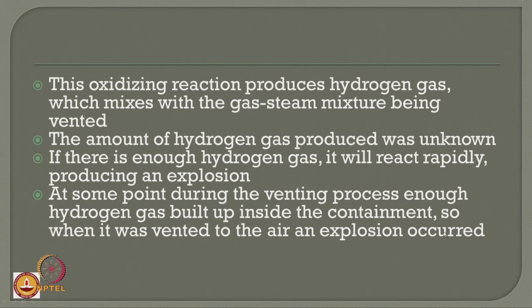So, you can see the series of faults that occurred. Earthquake started, earthquake damaged the reactor, it resulted in power shutdown, reactor was stopped, moderator rods introduced, there is no coolant supply available, external power was brought in, tsunami came, external power was damaged, there is no power backup available. After a few hours, people brought up battery supply, even the battery supply drained out, but they could stop the reactor, but they cannot stop the heat. They pump in water, they want to disable or relieve the cooling system. This water produced hydrogen gas, released pressure, resulted in explosion. You see, these are all a sequence of problems that occurred at one plant.